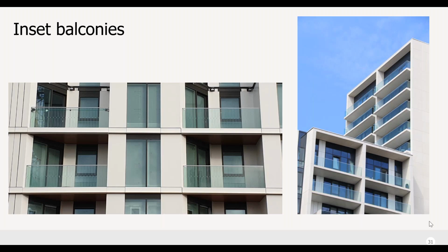Traditionally, these walls were expected to have positive drainage, but there is a lot of move towards using controlled drainage for these as well. Actually, they're protecting the building behind them rather than giving any further cause for water ingress, providing pattern staining is avoided by keeping the water outflow away from the adjacent wall surfaces. They can be very effectively controlled drainage. The right-hand picture there shows another type of inset balcony between projecting fins, which is becoming increasingly common.